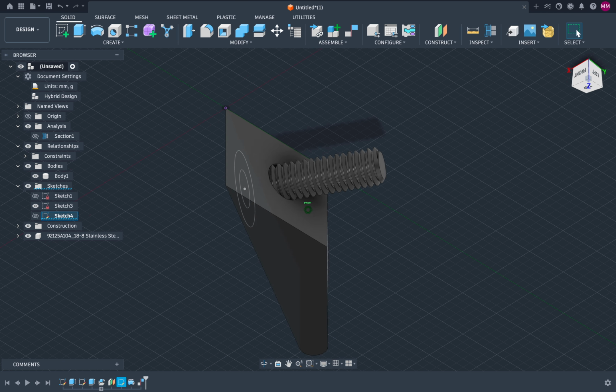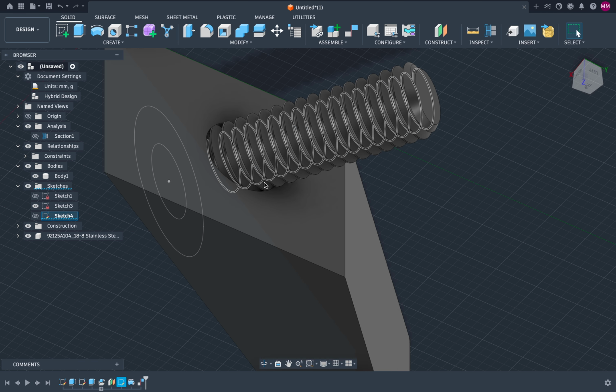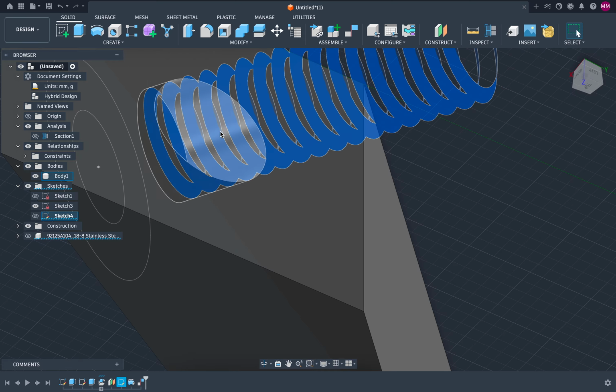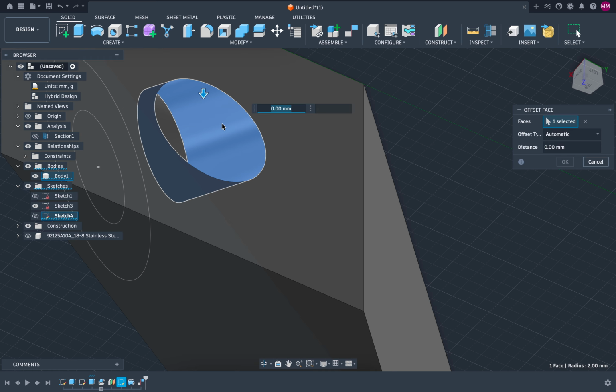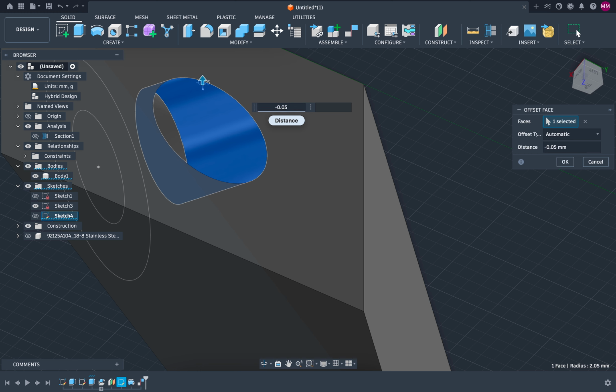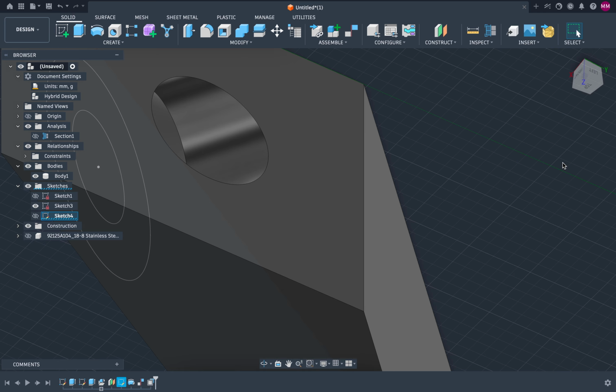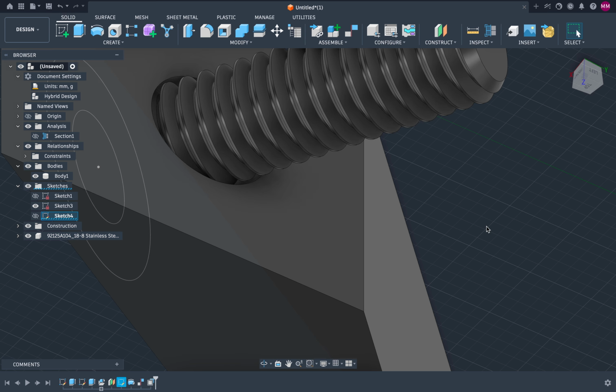We have our margins, and if we even want to give a bit of slack to this face that the bolt is touching, we can just go in here and move the face. So click on it and move it negative 0.01. Now it might seem that 0.1 of a millimeter is a lot looking at this, but it's really minuscule if you take a look at it on a ruler. So let's go back and unhide it.